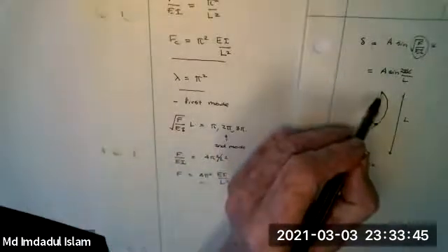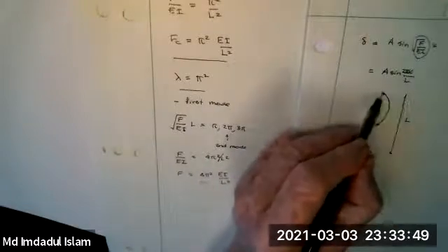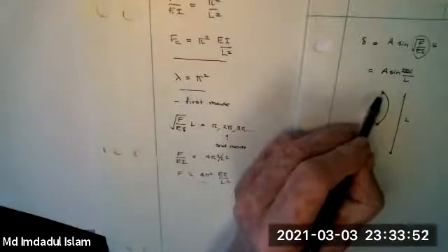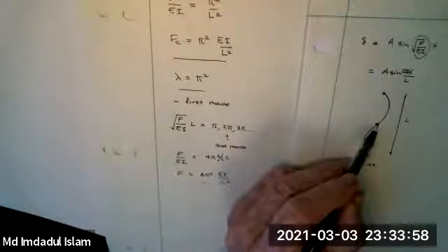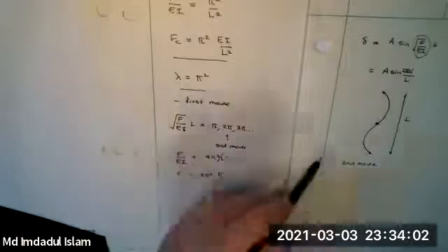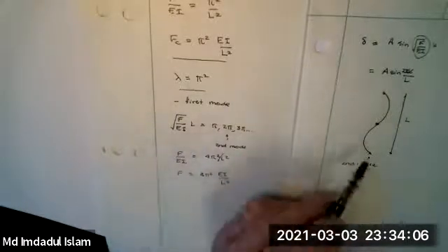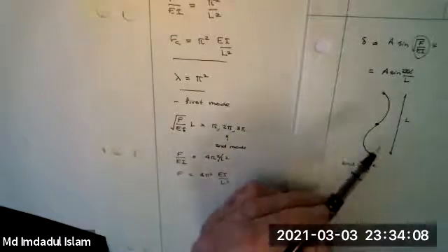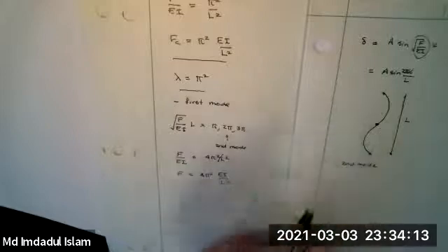This is a common technique for reducing buckling. If you have this beam or column, it's vertical, so it should be a column, and it's got hinged ends here, if you come in and put a support, a pin support in the middle, then your buckling load will go up by a factor of 4. Okay? So you can use this as a way of trying to beat buckling. This is a common practice. If you see something buckle, work up to the middle of it and clamp it there, and you'll probably stop the buckling.